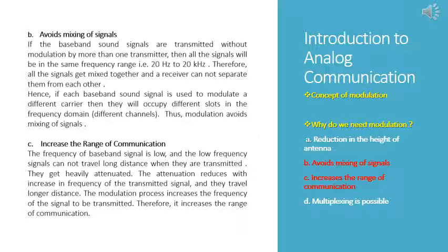If a baseband sound signal is used to modulate different carriers, we can shift the baseband signals to occupy different slots in the frequency domain, and modulation helps in this process to avoid mixing of these signals. And we have another point, which is that modulation increases the range of communication.